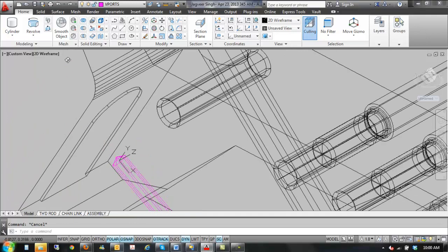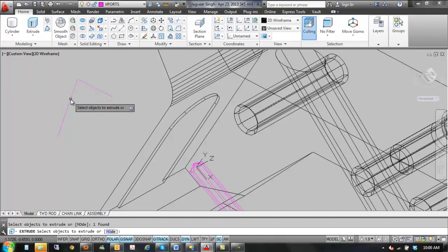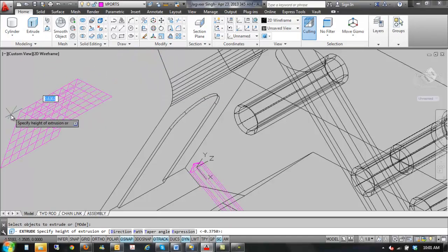And if you had a polyline there, let's just create a polyline. Now, that's a polyline, but it's not closed, right? If I extruded it, let's extrude it. I can extrude a line. See all the lines I get? Because when you extrude a line, you create a surface, right? What you're looking at right there is like this piece of paper folded in half, right? It's a surface. It has no real thickness. It's just defining a surface, right?